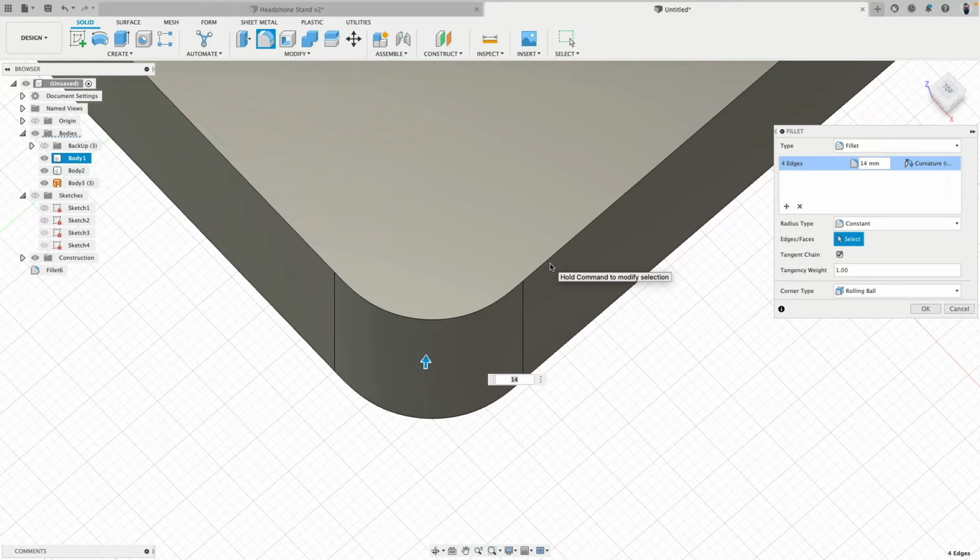But it can also be more computationally intensive. And in direct modeling, we can't adjust it so easily. So as a note for those who might ask, why do I use G1? That's because of the limitation of the direct modeling. With G1, I can adjust the radius. With G2, actually I can adjust the radius too later, but it is then reset to G1. So I just go with G1 from the beginning.